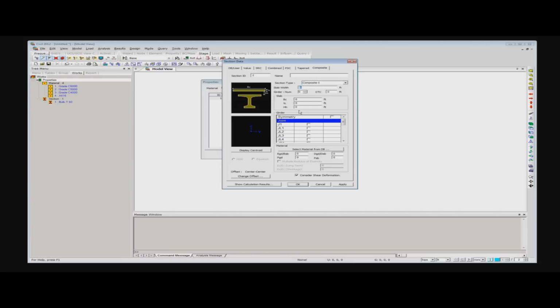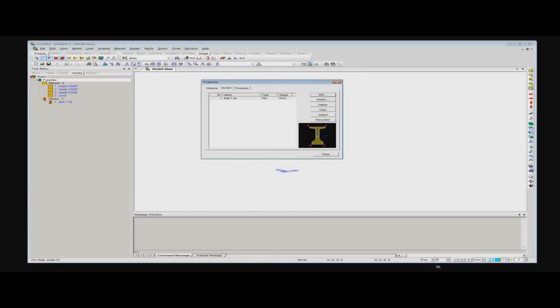Okay, so I need just to import my values for that. My slab width total is 900. Oh, I'm in the feet, so I gotta change it, because I have my values in inches. So I can switch it to inch. Another good feature of Midas Civil is that anytime during your modeling, you can switch your units from one to another without any change in your total model.